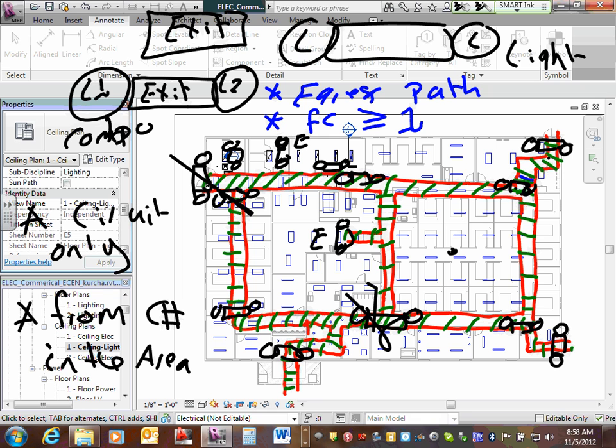It will do you no favor at all to circuit this emergency light from the circuit that feeds the bathroom. If you lost the power that's coming to the building, this will go on. But what if you put a troublemaker like Adam and go trip the circuit breaker that feeds this circuit here? Would this light go on?